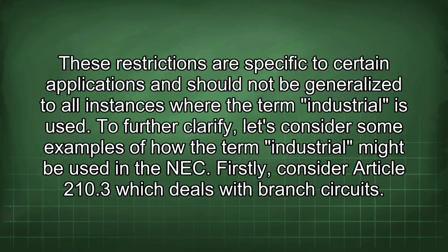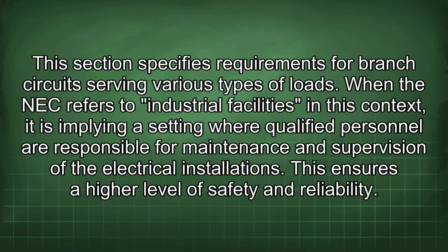Firstly, consider Article 210.3, which deals with branch circuits. This section specifies requirements for branch circuits serving various types of loads. When the NEC refers to industrial facilities in this context, it is implying a setting where qualified personnel are responsible for maintenance and supervision of the electrical installations. This ensures a higher level of safety and reliability.